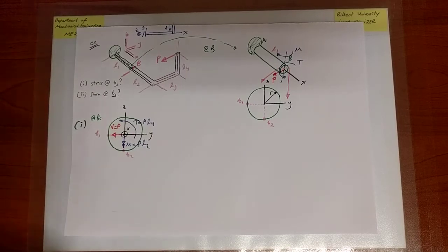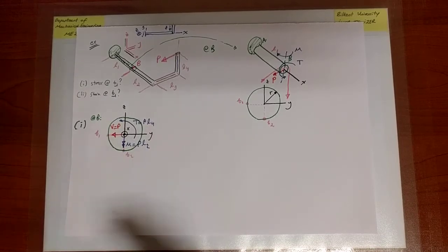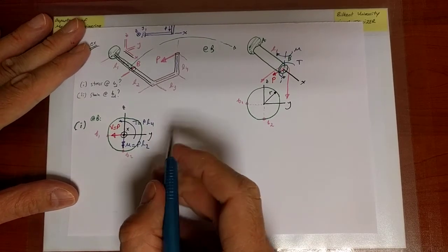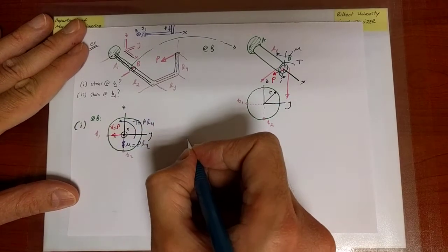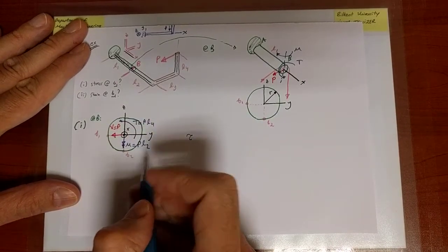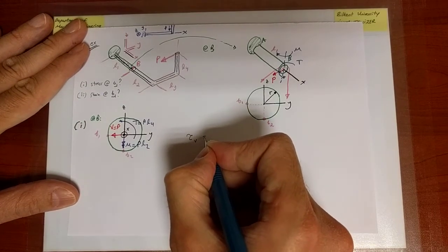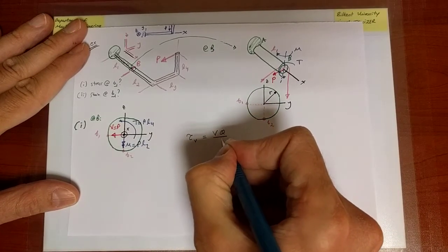point B1. Okay, so in general, we're asked for stresses, we will have shear stresses and normal stresses. So first, let's write all possible values that we could encounter. The first thing we could have is obviously a shear stress. There could be a shear stress due to the transverse shear force on this cross-section in general. And that would be a transverse shear stress that is, remember, in the form VQ over IT.